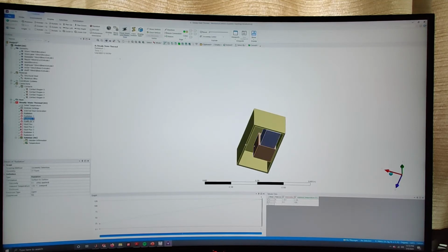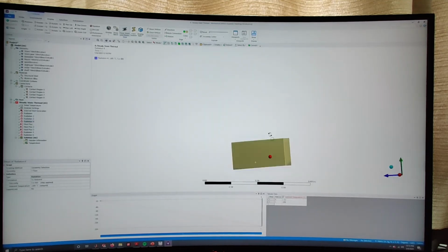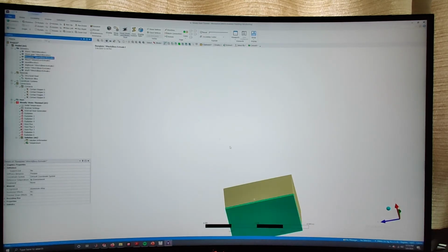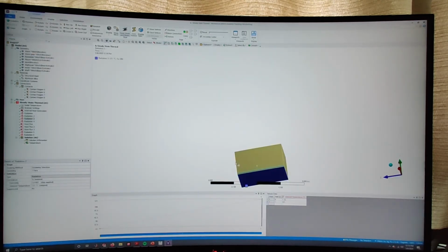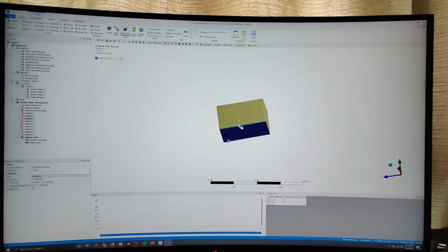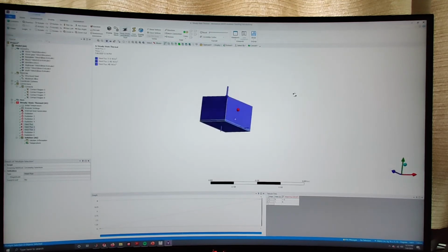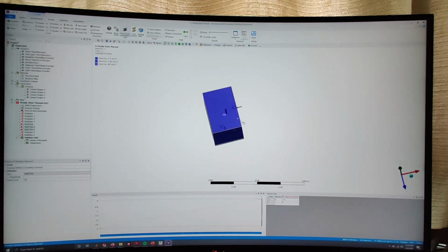Alright, and then with radiation 3 and 4, this is the top surface, and then this is the bottom surface. I can jump back to here. So this is radiating to the lunar surface at 121 C, and this guy is radiating to space at 4 Kelvin. Very cold.